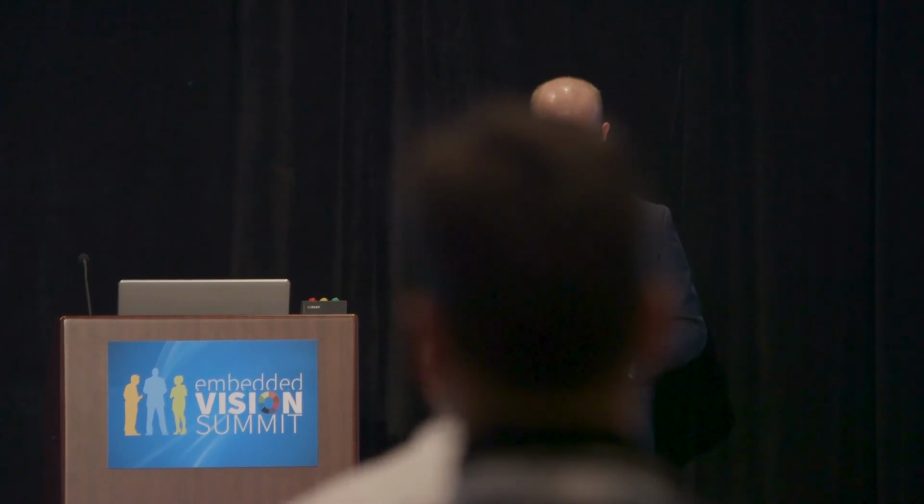A great example of that is if you point one of our stereo cameras up at a drop ceiling and you start rotating it very quickly, the small texture of the drop panels disappears first, but you still have the big bars between the drop panels because those have enough visual texture that they hold up even with a fair amount of motion blur in the camera data. But that is something you have to watch out for. And definitely use a stereo system with a global shutter. Rolling shutters cause all sorts of other bad issues when you're moving.